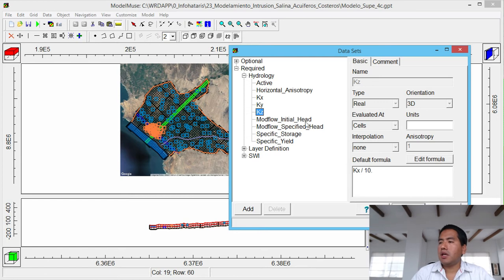Okay, the initial head is model top -2 because if you run it with model top at the beginning of the 100 years, you are saying that the model is completely saturated, and then you will have evapotranspiration in your whole model, and it will bring you numerical instability because evapotranspiration will have a huge value. No? Initial storage, specific storage, this is the most relevant, I think, is one. No, I think no. Maybe I'm wrong. This is 1.2 10 to the -5. Specific yield is 0.12. Okay.